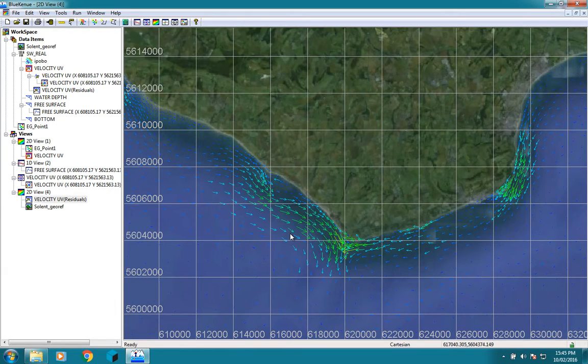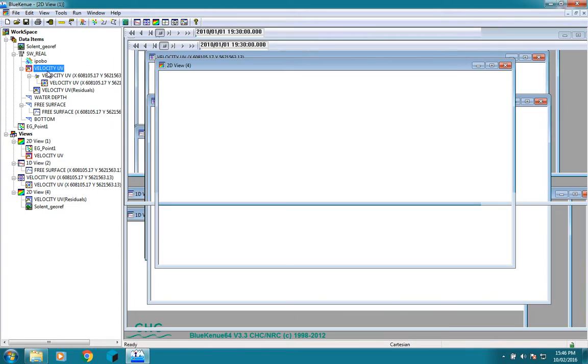Okay, now what we're going to do is calculate shear stress maps, and this is kind of a measure of the friction caused by the water acting on the bed. And again, this is important because it affects sediment transport and sediment movement. For a fluid to begin transporting sediment at rest on the surface, the bed shear stress must be exceeded, so it's critical shear stress. Now what we do, like before, it's very easy.